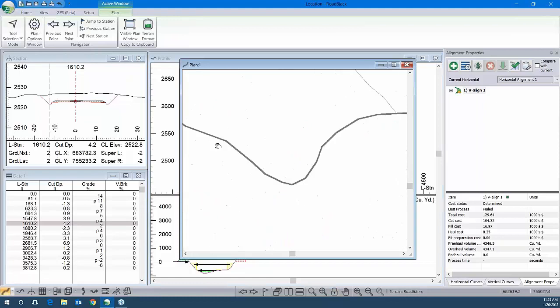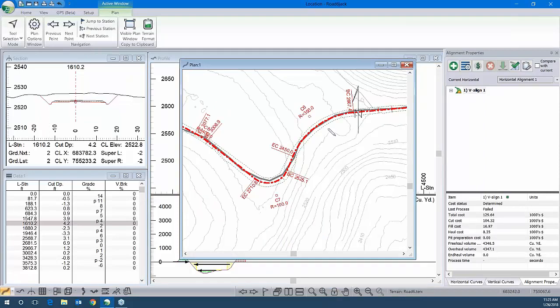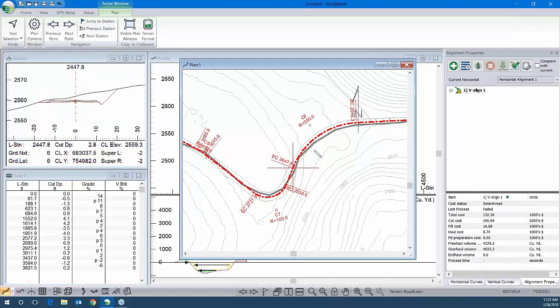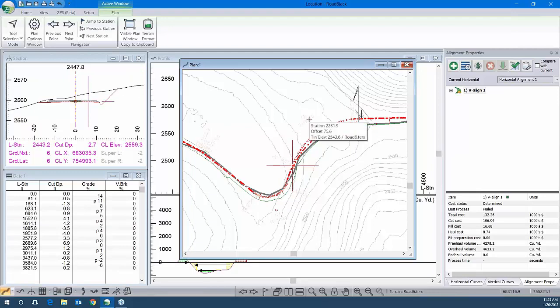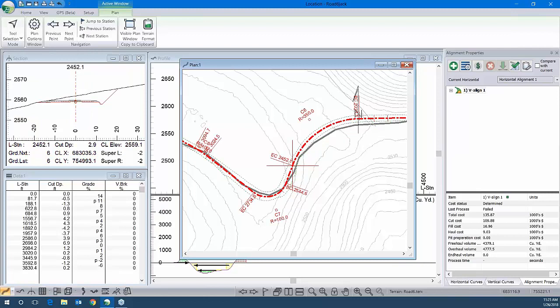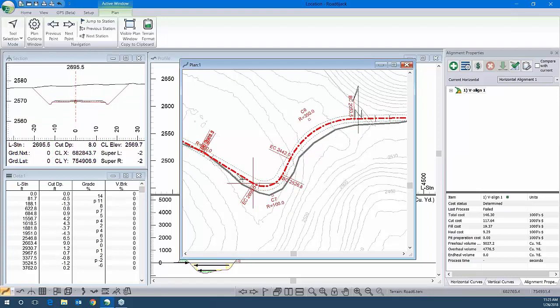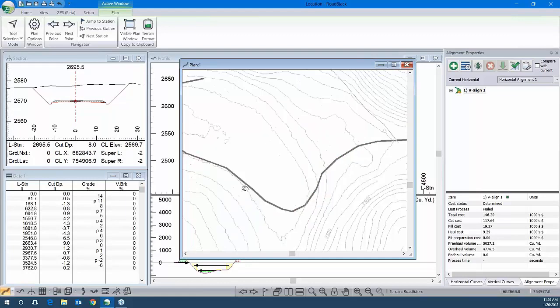Let's say you wanted to try a slightly different route, or a different route totally. And see the cost changed again. If I pull out a little bit more, it's at $132,000. Now it's at $135,000. Try cutting a little bit less here. Sorry, avoiding less, just going straight through instead of having to worry about going around these contours. Now it's $146,000.